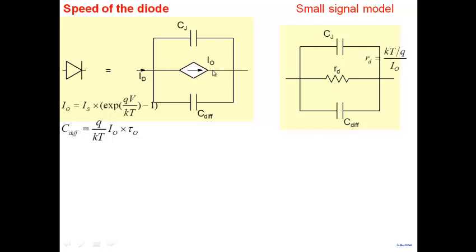But then, besides I naught, what else do you get? You get a capacitance. Any current which flows through the capacitance is something that you don't want normally. You want this current. You are interested in this part here. Anything which flows through here is an unwanted component. And when significant current starts flowing here, it begins to distort your characteristics. You want the characteristics to be dominated by I naught. That's the diode. That's what causes rectification. It's not this here. In fact, this is something that you don't want.